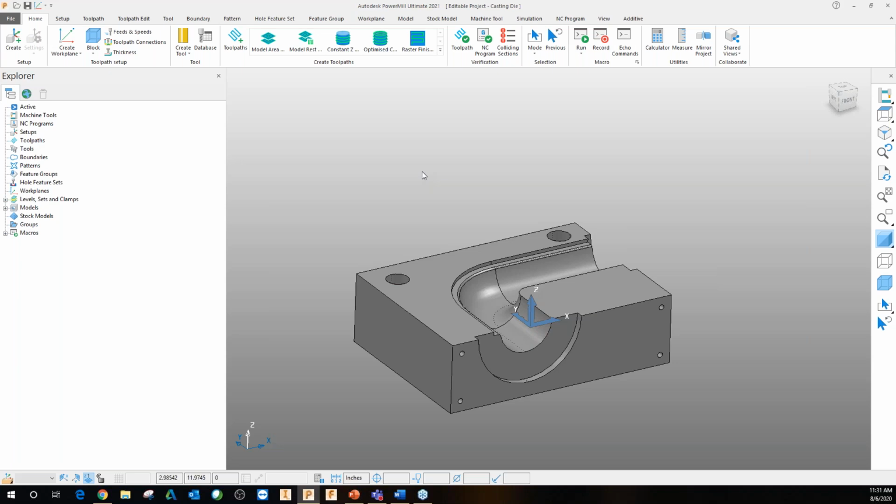It's going to create a roughing strategy. It's going to do a rest roughing strategy, so a secondary roughing operation. Then it's going to apply a steep and shallow toolpath and go through generating from start to finish. So once I load the macro, it's going to step through each of those all the way start to finish without my having to do anything.